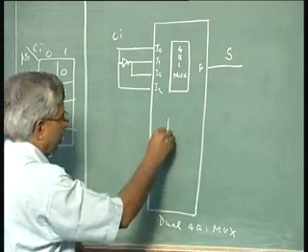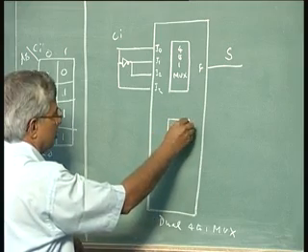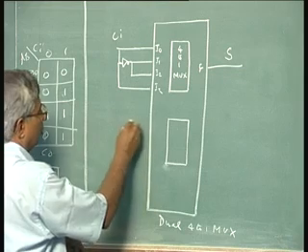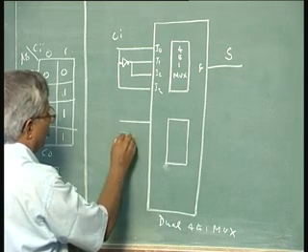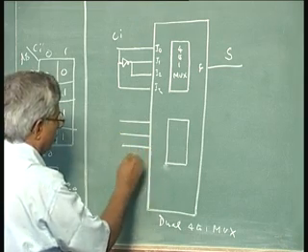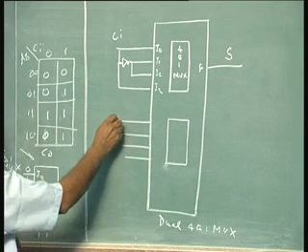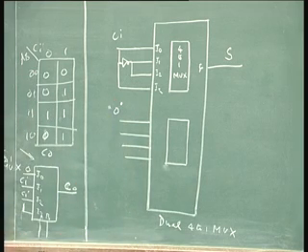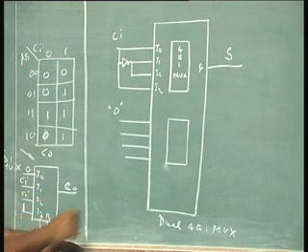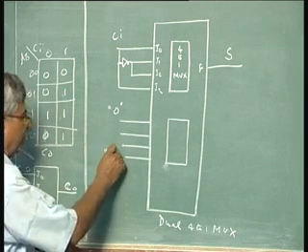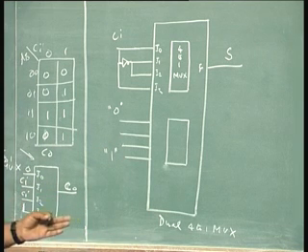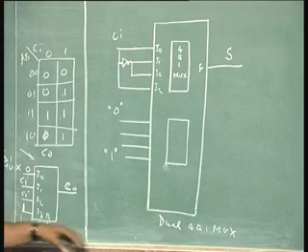We have another 4 to 1 mux here. This will be connected to 0, that means ground. When you put 0 in inverted commas, that means a ground potential, 0 potential. And this 1 means it is the VCC, whether it is 5 volts or 3.3 volts, whatever the operating voltage is, that voltage will be given here, and the ones in between these two are connected to Ci.